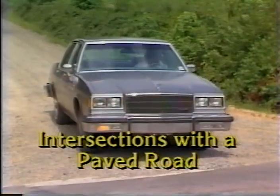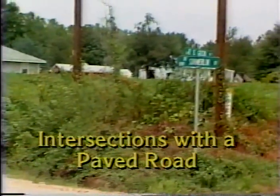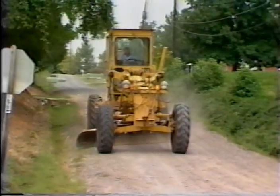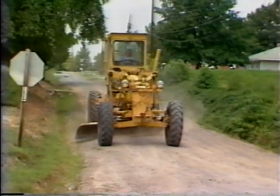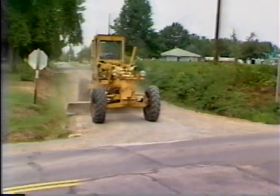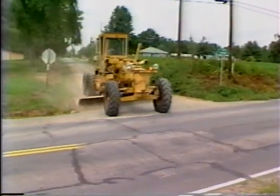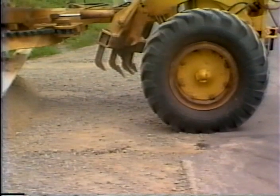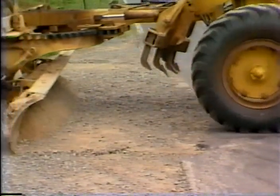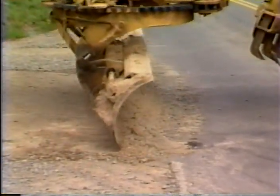The next special condition is an intersection of a gravel road with a paved road. Again, gradually eliminate the crown on the gravel road, beginning 50 to 100 feet back from the intersection. This transition is smooth, with the crown being totally eliminated at the intersection point. Do not leave loose aggregate spilled onto the paved surface. This creates an unsafe condition for motorists on the paved road.